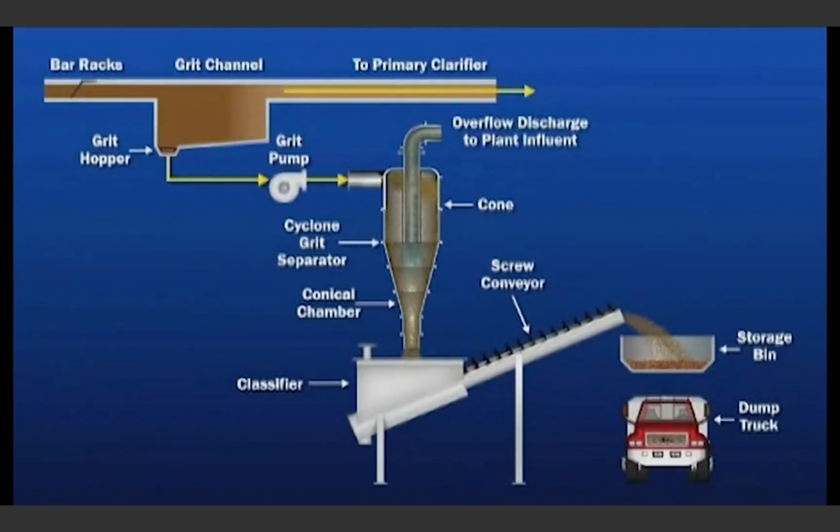Another method for removing grit is a velocity system that uses centrifugal force to separate the liquid from the solids. The solids are extracted from the outside edge of the spinning mass, while the liquid stream flows up and out from the center of the chamber under pressure.